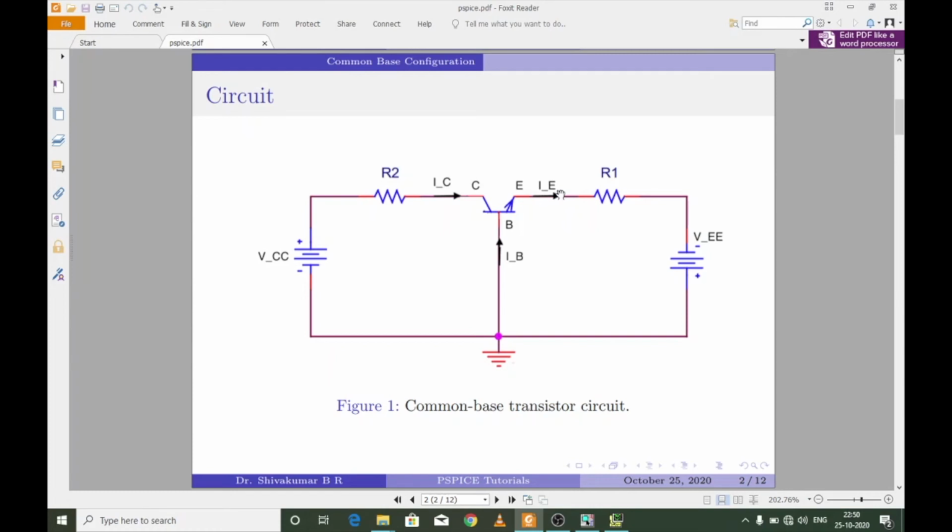Now, since our voltage across the base to emitter is varied from 0, the only way possible in order to get a saturation characteristic curve for this particular transistor configuration is to apply a negative voltage across the VCC. Now, since for any practical DC device, it is not possible to connect it in this way and still apply a negative voltage, the saturation characteristic curves for a common base transistor configuration are not practically derivable.